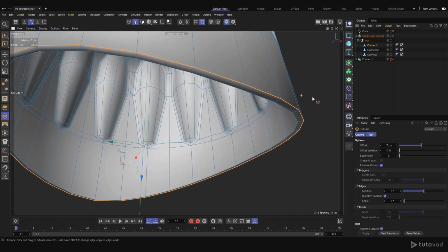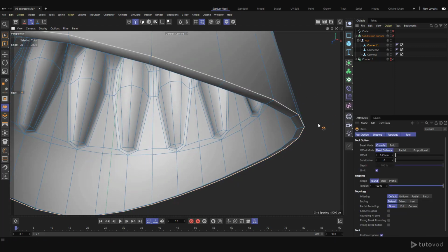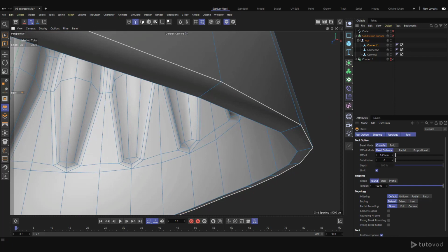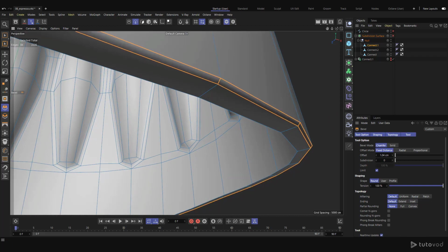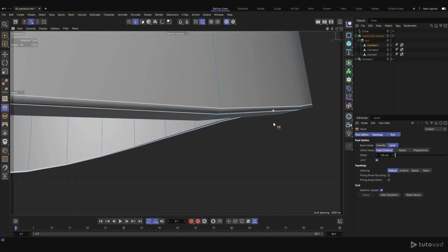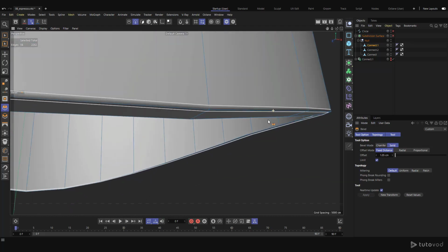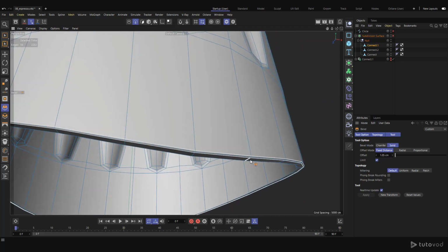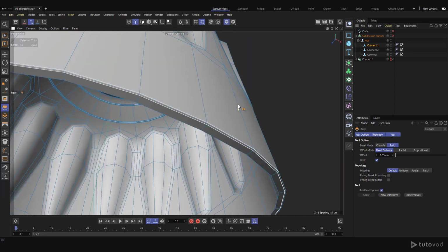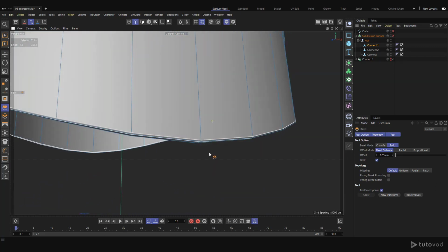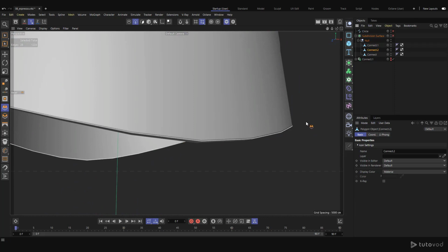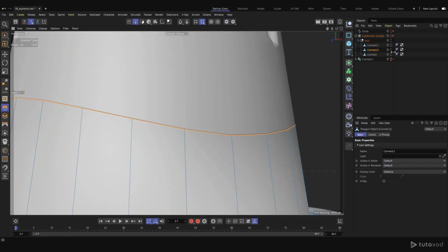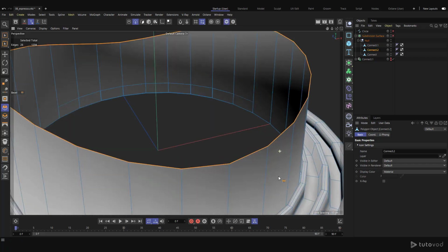Let's double click, and here I'm going to use the bevel. So for my bevel, I'm going to add something like that. Here, what I'm going to do is to select the solid mode, so we get something like that. So get this value, can copy this value, so we'll use it at the bottom. So you can go here, select this one and isolate it.